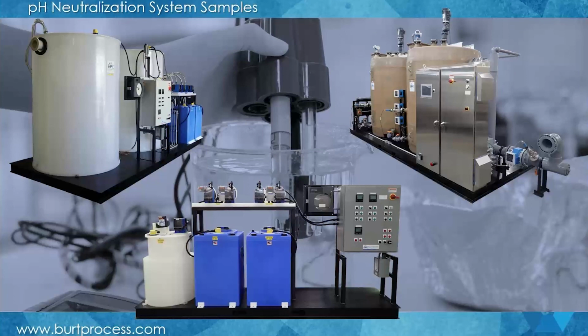We've talked a lot today about some of the different theories that have been involved, and a couple of different standard pH systems. There's a lot of customization that goes into these types of systems as well. You can see here in the upper right-hand corner, this is a fiberglass treatment system. This is for high temperature waste, as an example, as a two-stage style system. Down here in the lower corner, this is more just a reagent-based system, for if you have an outside tank that you want to inject into. This is often utilized as well. Sometimes people have an outflow condition and they'll reuse an existing tank. That's where these types of systems come into play.